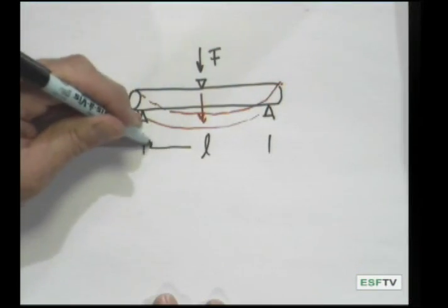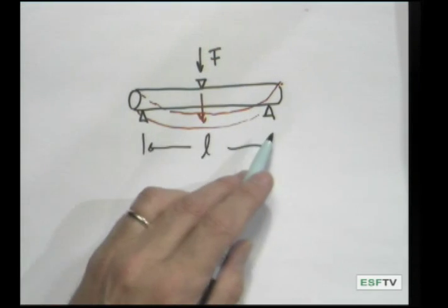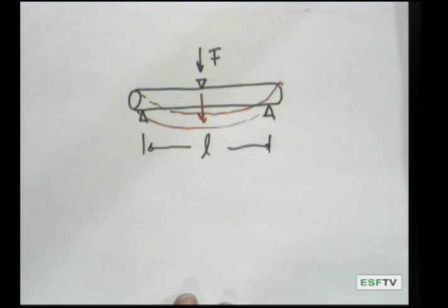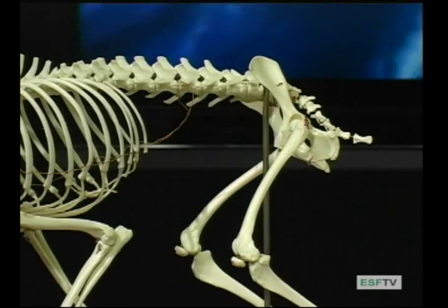Now, the flexural stiffness of an object, this is where properties like the length and the size of the bone or the rod come into play. For example, if you look at the kinds of dimensions that affect the stiffness of an object, one important one is the length of the object. In the three-point test, it's between the 2 pivot points on either side. But in the case of Twiggy, the length is going to be basically the length of the shaft of the bone.